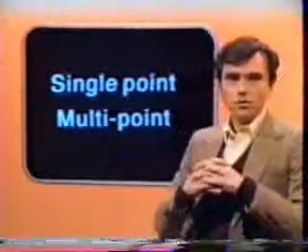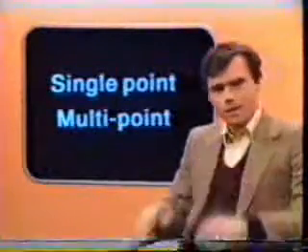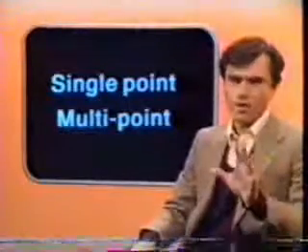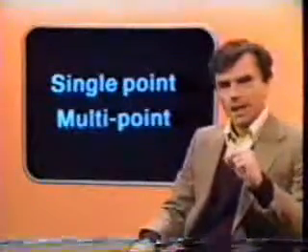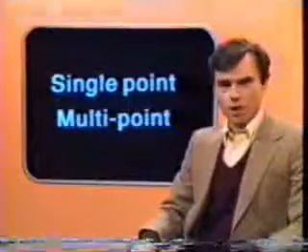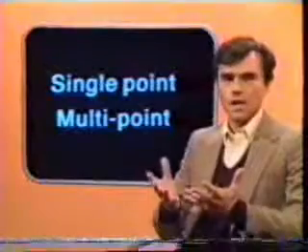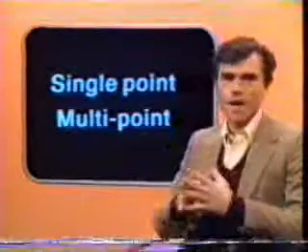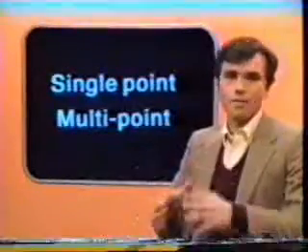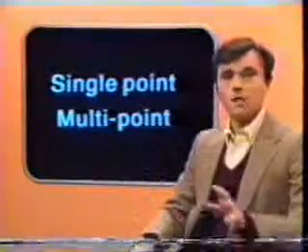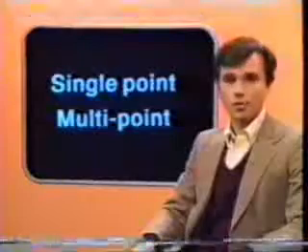The types of valves to be used for intermittent lift depend upon whether we are going to install a single-point or multi-point injection system. In single-point intermittent gas lift operation, all of the gas necessary to move the liquid slug to the surface is injected through the operating valve, generally the bottom valve in the string. Let's look at single-point injection on the gas lift simulator at Gulf Oil's New Orleans Training Center.